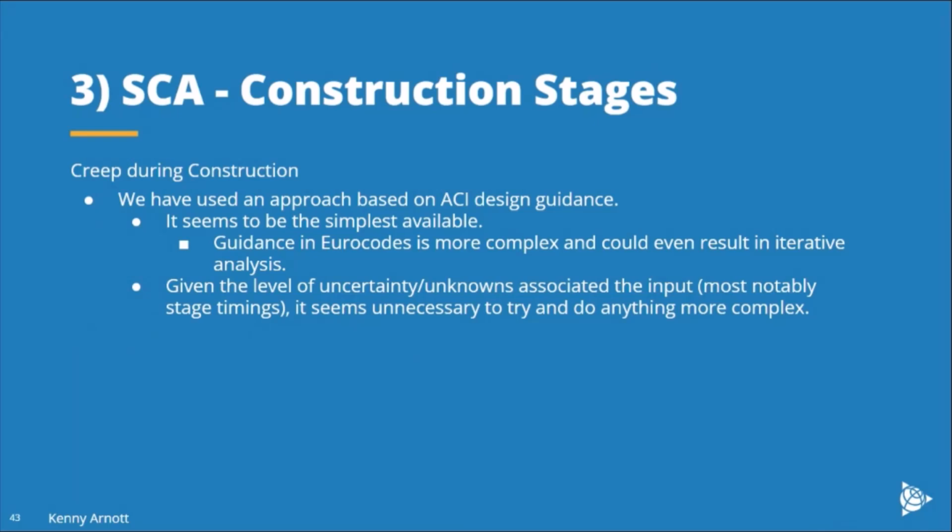There is guidance in Eurocodes, for example, which is more complex and would inevitably need us to make it an iterative analysis. And it seems to us that given the level of uncertainty in all sorts of things to do with stage construction, but in terms of the creep, for instance, your uncertainty in terms of things like the stage timings has a bigger impact than trying to be very academic, if you like, in terms of the level of effect that creep has.